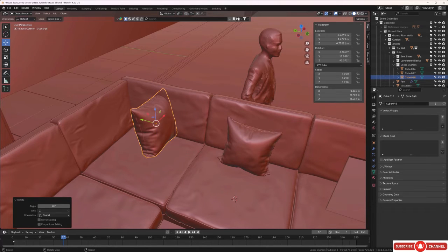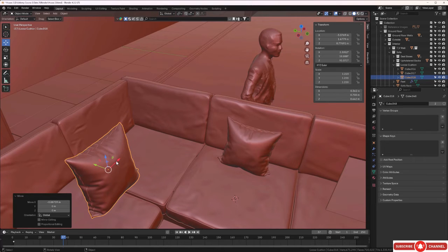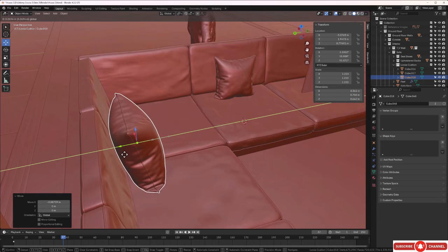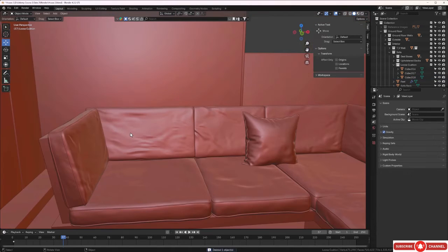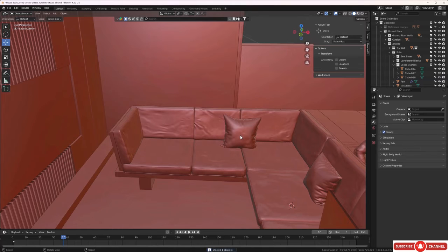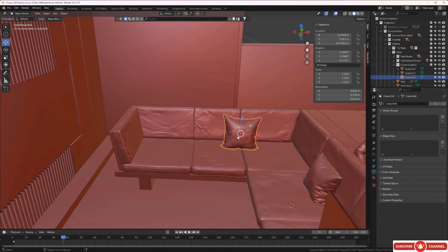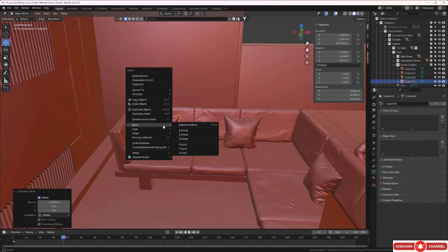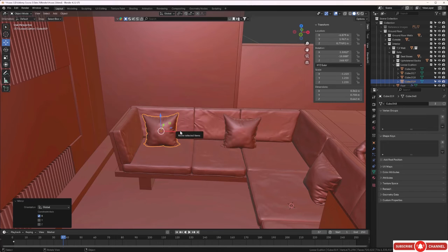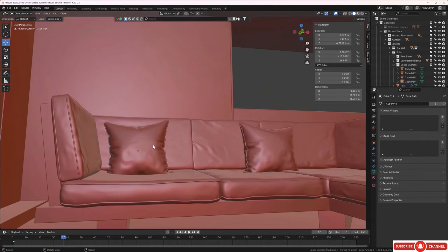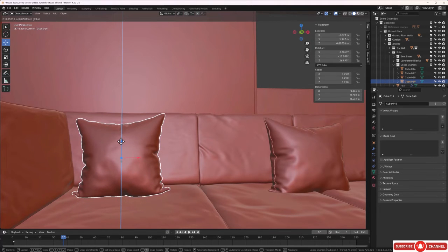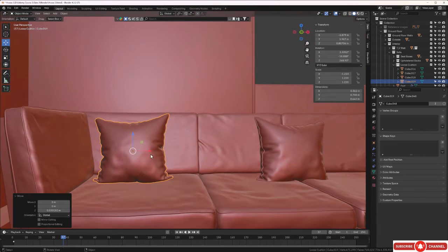With that done, I'm going to rotate that, so I'll press R Z 90 enter, and I'll bring this one over and drop this somewhere else. Okay, I'll put that one here like this maybe. So now I'm going to make a third copy, so I'll grab this and I'll press Alt D and X and bring this over like this. But so it doesn't look identical, I'm going to right click and go ahead and mirror in the X axis, and there we go. Maybe we just need to take this up a little. Let's have a look. And there we go, that's cool now.